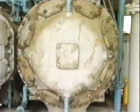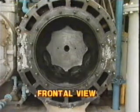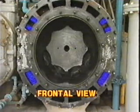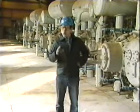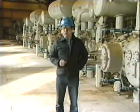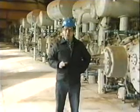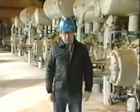When gas is compressed, it generates heat. So to help control heat buildup and prolong cylinder life, cylinders have passages for cooling water. Keeping things cool is vitally important in operating a reciprocating compressor, because excessive heat buildup can damage equipment, resulting in lost revenue and costly repairs.